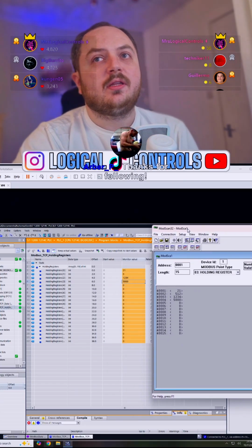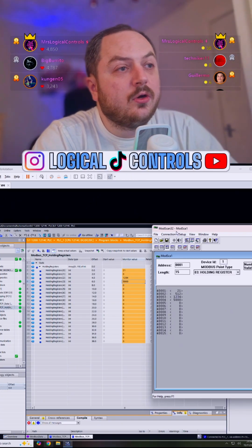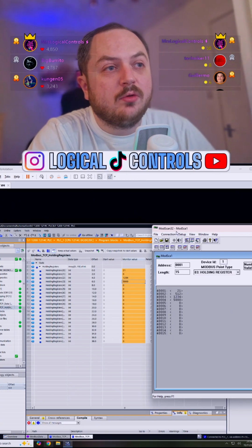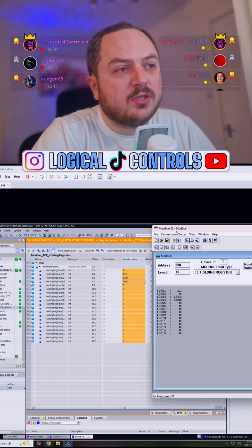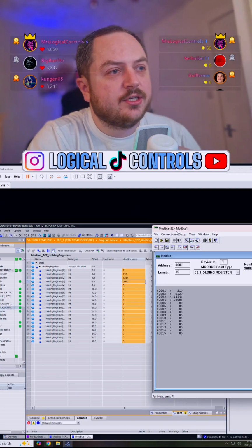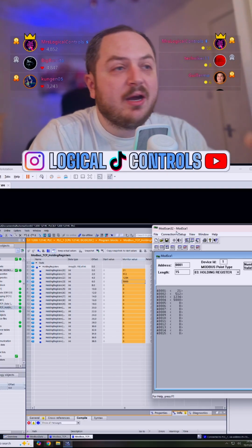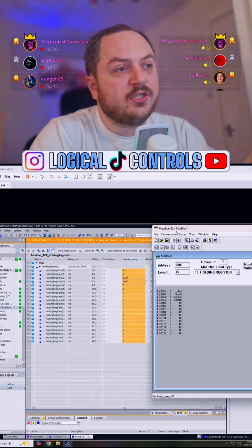The times when you would use Modbus more often than not is if you have a PLC that would be your Modbus master or your Modbus client, and you might want to read data. For me, I work in power generation. A lot of the time we read data from meters, energy meters, power meters, that sort of thing, which are by a different manufacturer.